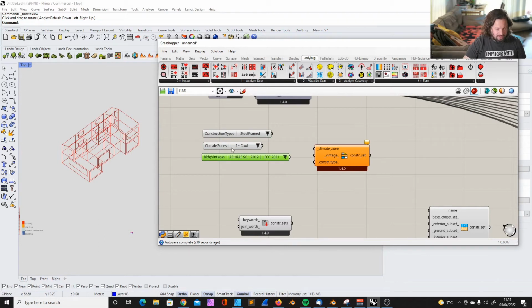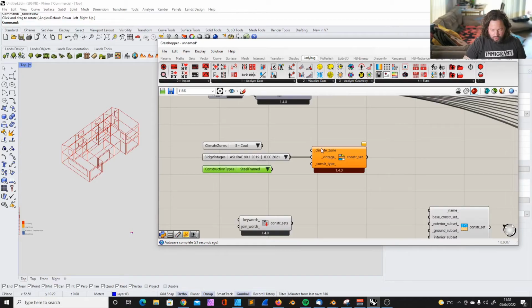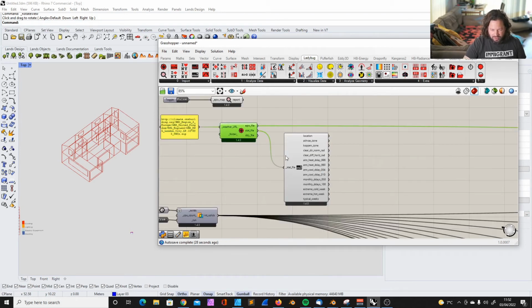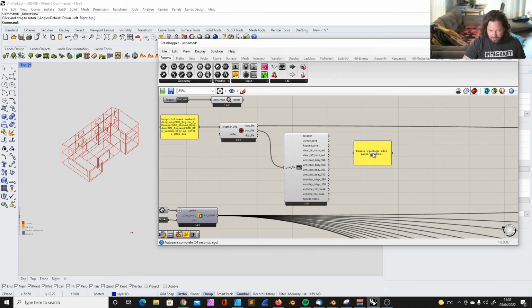Let's assume this is going to be a new building, and we just use the latest standards. So we could choose here. If it's an older building, we might choose somewhere from here. And if we know the building standard, then we can select from here. Let's assume it's the latest, built with the latest building standards. And then we need to find the climate zone. The problem here, as I tried to explain before, is that a STAT file will normally give us the ASHRAE zone, and it's just a number between 0 and 8. And then there are letters devoted to wetness, A, B, and C. And I Googled it already, I checked what London is, because London isn't here, that's the problem.